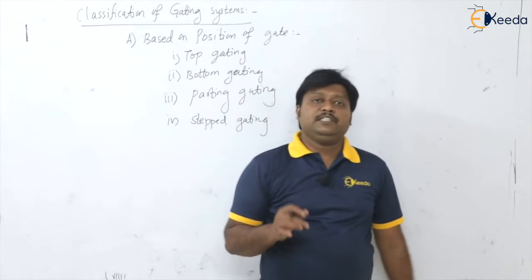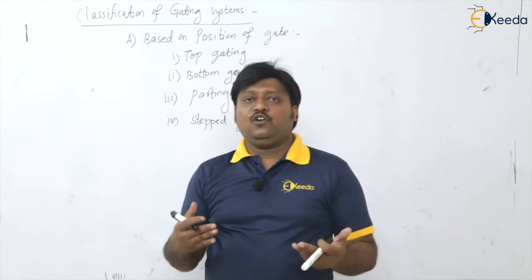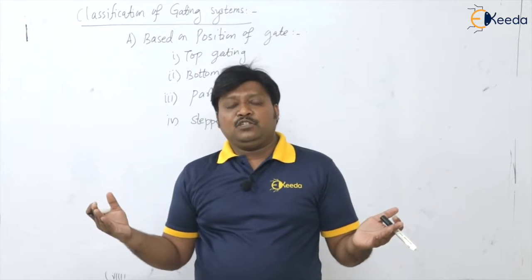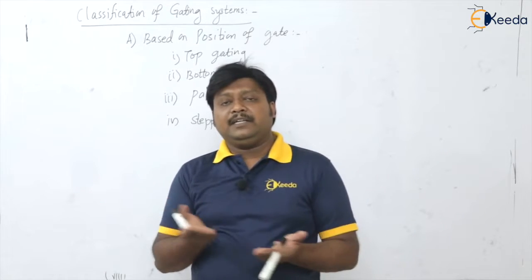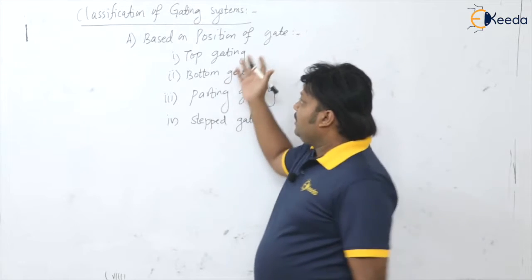So these are the classifications based upon where your gate is positioned, whether it is at top, at bottom, at the parting portion, or in the horizontal plane or parting plane, or the number of gates, that is the stepped gating system.